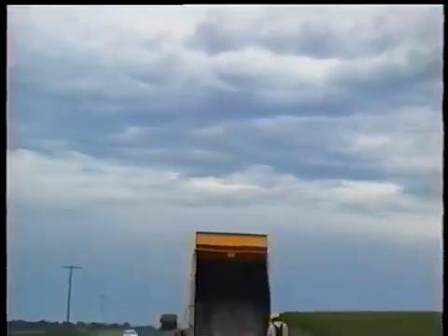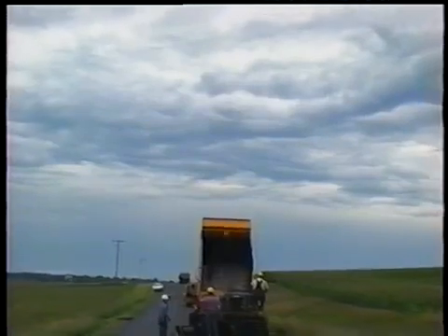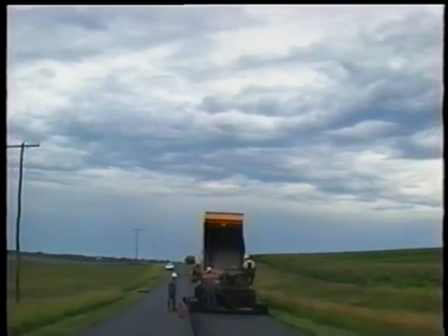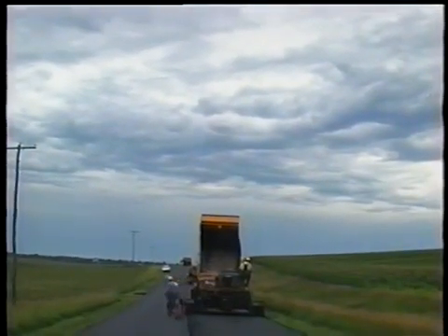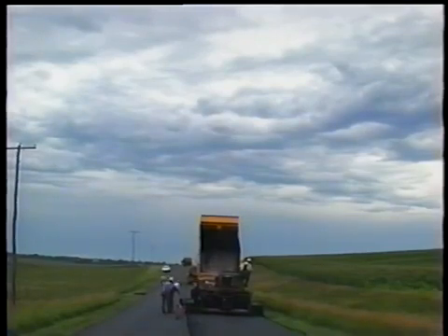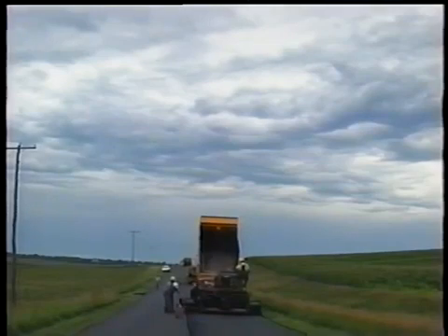Precipitation is a concern. Asphalt paving should not begin when rain is about to fall or too soon after it's fallen, while the surface is still wet. Occasional sprinkles or passing showers have to be dealt with according to their volume and duration, from working right on through the minor ones to temporarily halting for the more serious ones.